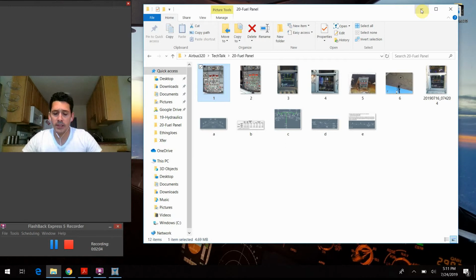One of those things is that the fuel system also provides cooling for the integrated drive generators. There's a system on board the airplane that recirculates this cold fuel that resides out in the wing during the course of a normal flight. As you'd imagine, the outside air temperatures keep things very, very cold. So we can use this cooling. We circulate this fuel past the heat exchanger in the IDG, and that cools the IDG oil. It's an interesting design and kind of a genius thing they incorporated, but once again, something you might not have guessed.